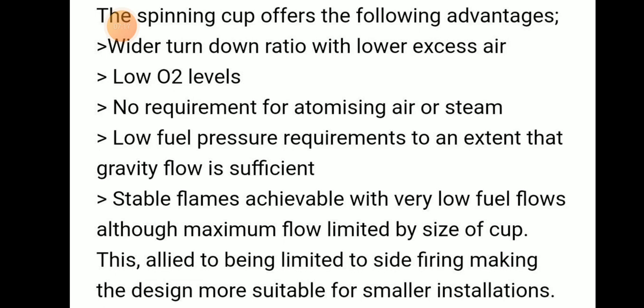To summarize the advantages of the spinning cup of the rotary cup burner: a wider turn-down ratio with lower excess air, low oxygen levels, no requirement for atomizing air or steam, low fuel pressure requirements to the extent that gravity flow is sufficient, and a stable flame achievable with very low fuel oil flows, even though the maximum allowed flow is limited by the size of the cup. It is limited to side firing, making the design more suitable for smaller installations.